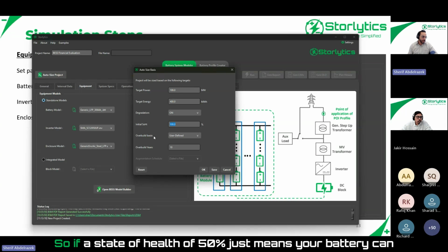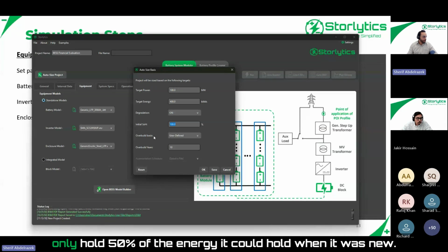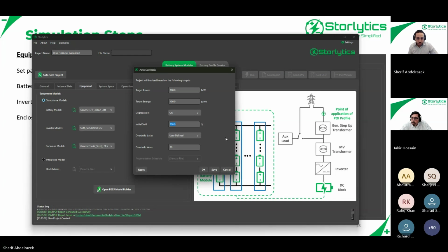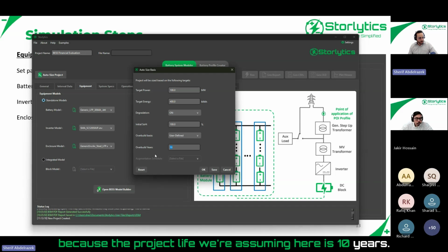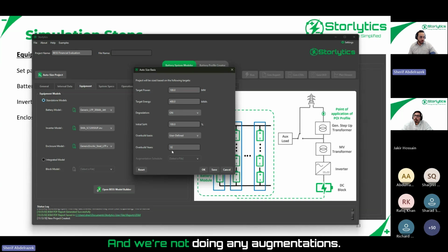So a state of health of 50% just means your battery can only hold 50% of the energy it could hold when it was new. Over build basis here, it's user defined, like we said. Over build years, 10 years, because the project life we're assuming here is 10 years, and we're not doing any augmentations.